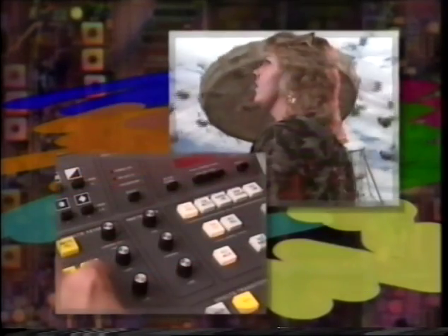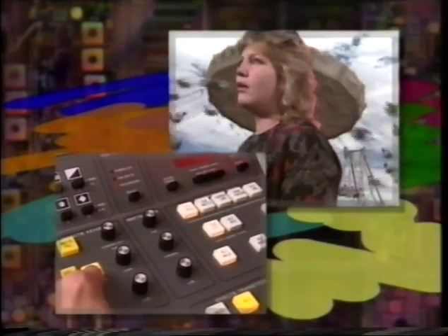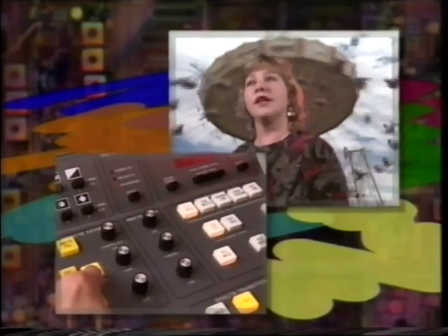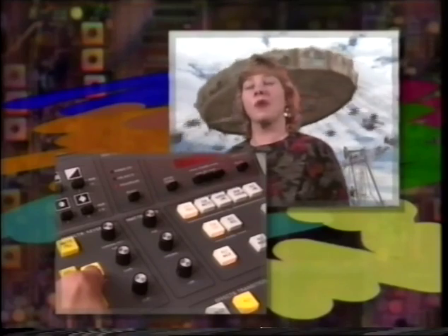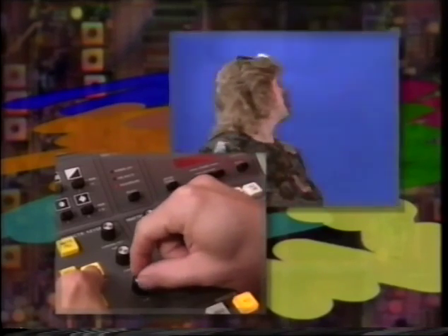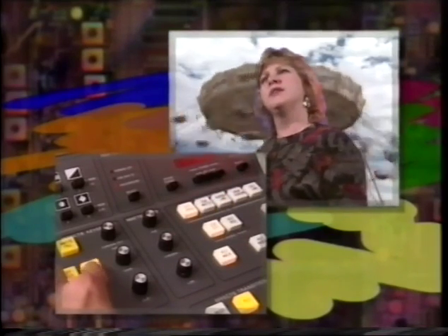When the chroma key push button is held down, the chroma and luminance controls are delegated to control the background color suppression and background color cancellation, respectively. The matte background settings are not changed. You may need to adjust the clip, gain, BCS, and BCC settings several times to achieve the best key. When you are pleased with the results, release the chroma key push button.